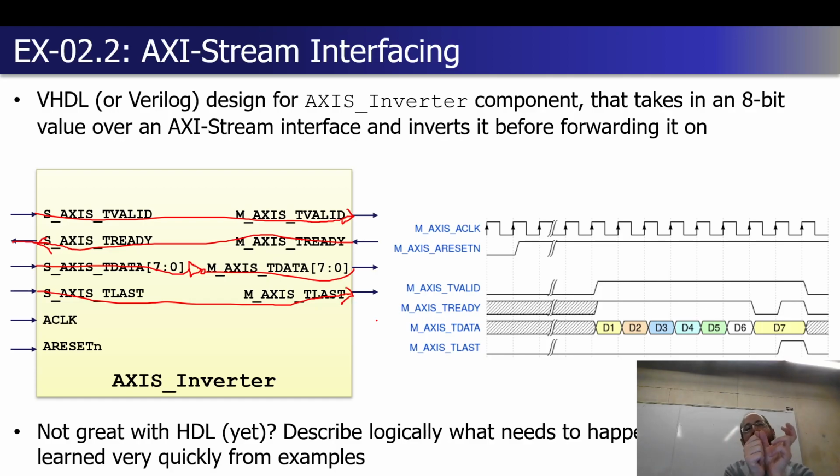And then it needs to add a base address to it, which is the frame buffer base address. That's going to be in one of those configuration registers where you're saying, currently you're writing to address 1 million as our base address, or whatever it winds up being. It's a constant in the driver. We've been writing to that. Oh, I'm done with my frame. Now let's switch what your base address is.